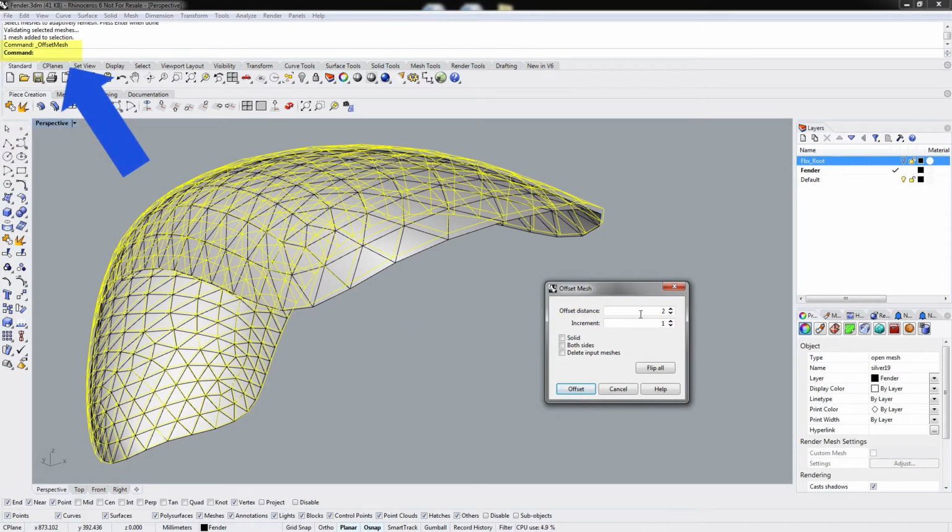To do this, we choose the Offset Surface command. 20 or more layers are not uncommon for some parts. In these situations, the surface geometry changes enough such that once the surfaces are offset, the different layers will be flattened individually. We are only going to do 3 layers in this demonstration, but rest assured, if you produce more, you can flatten and create patterns for them all in the same way we are showing today.